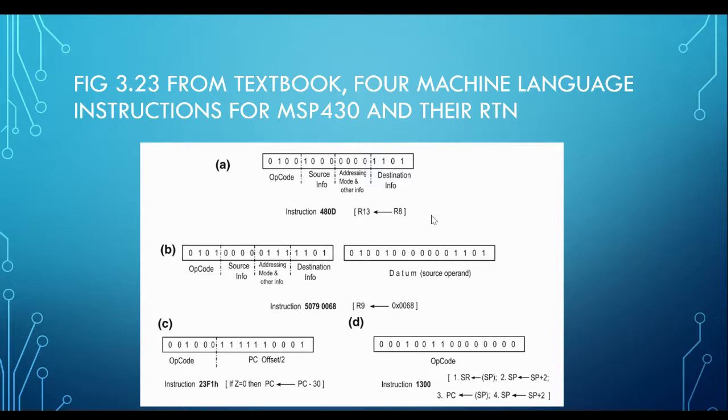So the computer will extract 480D from your memory, and this 480D represents this thing. Which opcode, you guys can explore yourself later, but generally a question can come out: it's a 16-bit opcode, these are 16-bit instructions, what do they mean? Probably they will give you a table, so it means extract this from this, using what addressing mode and what operations. So this is machine language, it's an instruction. When you compile, this is what you see.